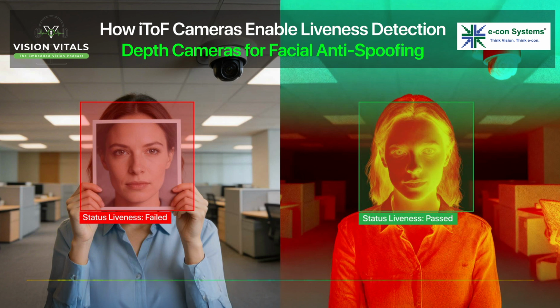So Depth Vista Helix is Econ Systems' 1.2 megapixel CW iToF depth camera based on the onsemi AF0130 sensor. It provides synchronized depth, IR, and confidence outputs, which are what biometric solution providers need. On the depth modes, it supports a 1.2 megapixel mode optimized for 0.2 to 2 meter capture range, which is right in the sweet spot for close-range facial capture at a terminal or kiosk.